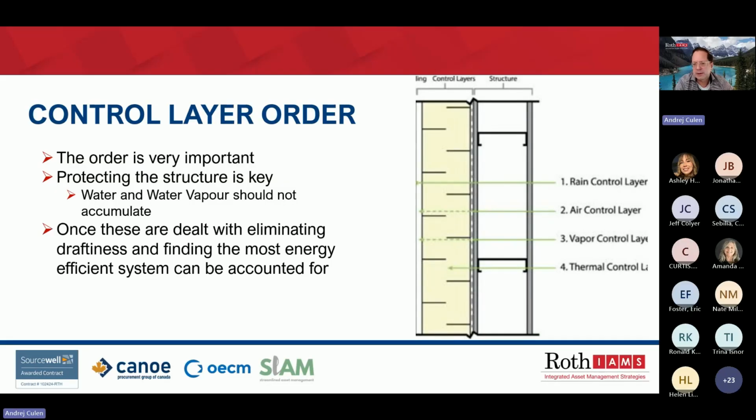A leaky building is an immediate problem. Over time, it can rot the structure. Buildings with drafts are very uncomfortable. Water vapor should not accumulate inside the building envelope walls. This can lead to mold, rot, and worse, hidden structural damage. For energy, we need insulation, needed to reduce energy flows.